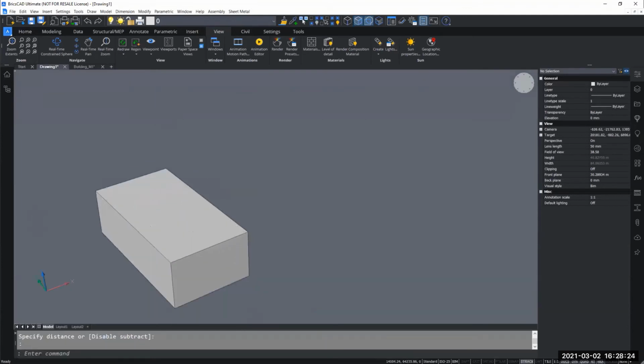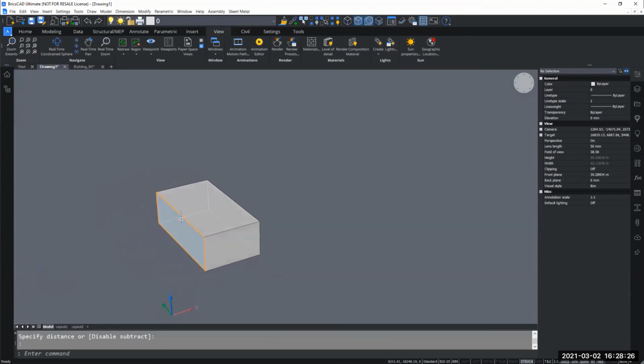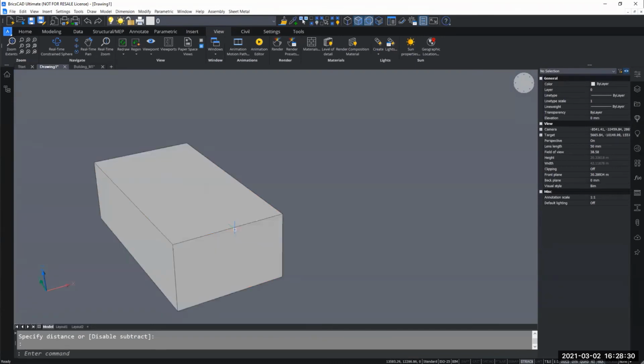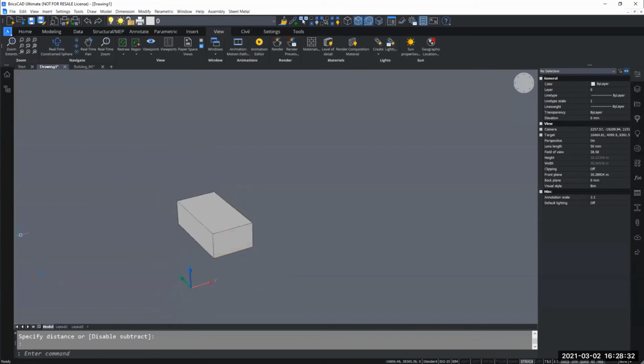So that's fine for selecting a face, but what if we want to select the entire solid, or just an edge? Well, we have those different selection modes that we've talked about earlier with edge, face, and boundary, and different combinations. With the prioritized selection of faces and boundaries turned on, by default I'm hovering over a face.